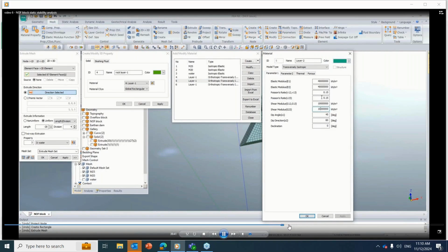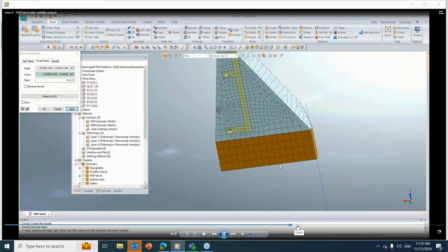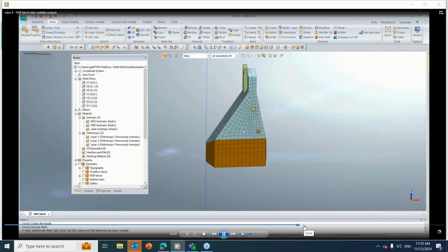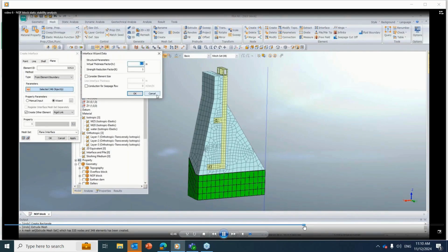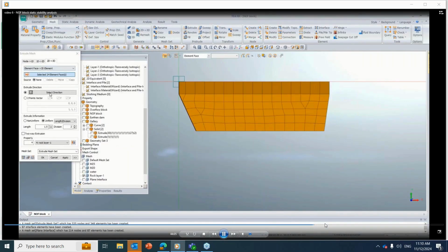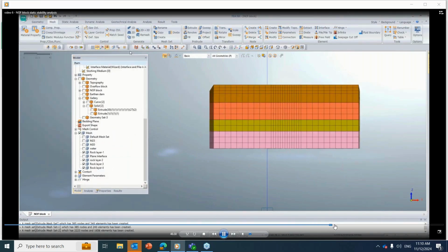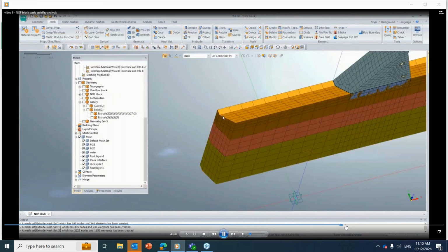That means almost 2 times the height of the dam I had modeled along the flow. Initially that should be considered enough so that the prominent deformation bulbs are within that modeled ground. So we'll check that in today's session, whether our prominent deformation bulbs are within that ground or not.